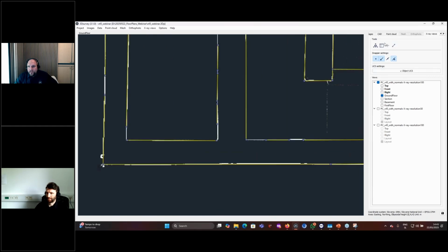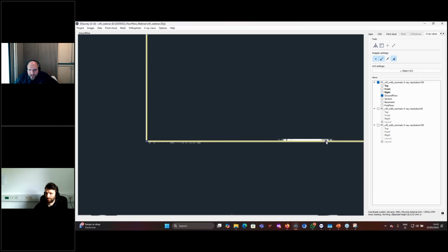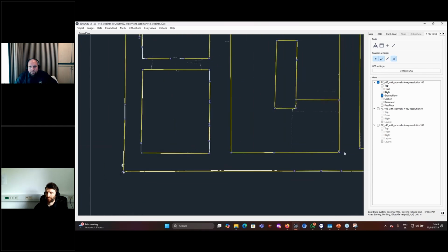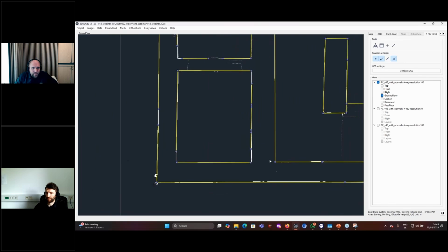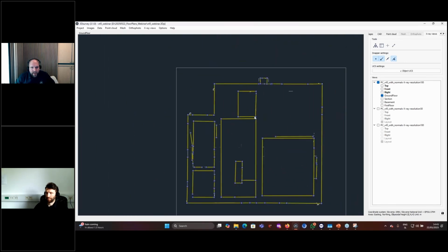But you also get a simple option. You can just select a line on the point cloud, just select a vertex like that, and just move it here. So here you get point snapping. Here I have enabled snapping on points or on the lines. You can just do that, this and that. I wasn't careful enough, like that. And now I fix this too. And you can go around and fix everything like that, and you will end up with a nicely defined floor plan.